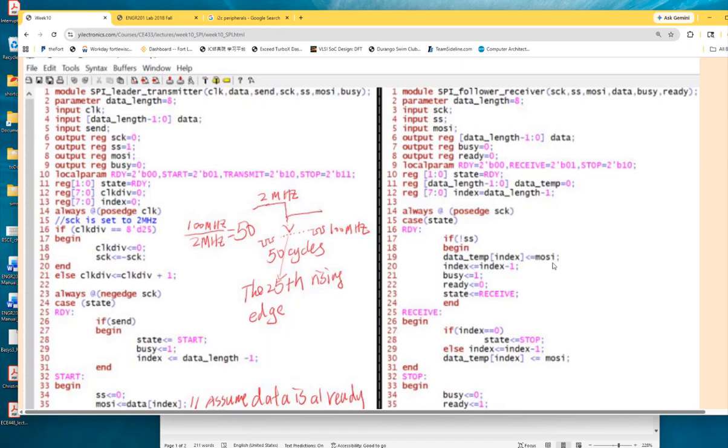How? Whenever you are sending data to MOSI, every single sensor is responding. They are feeling everything is being treated the same way. Hey, you are sending data, let me receive it. Every single one is doing the same thing. How would you be able to make a difference? Could you make different chip selects for each one? That's right. But how?